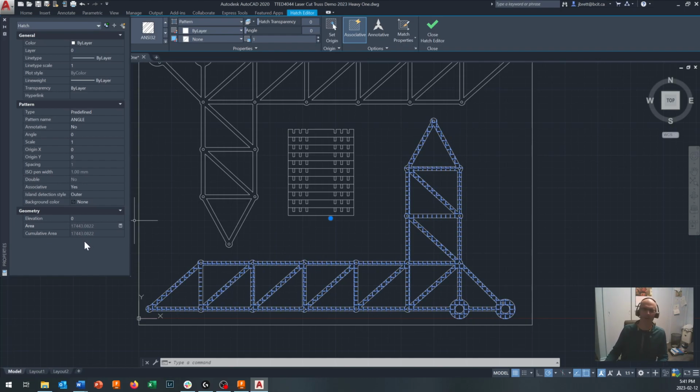You can actually determine that by taking a few very simple measurements in class. I'll leave that up to you to get a perfect value for the density so you can make a perfect mass estimation. But there you go. Just do a hatch and then the properties command, select the hatch. That gives you the cross-sectional area in square millimeters, multiplied by the thickness. Remember that you do have to convert from cubic millimeters into cubic centimeters, and that is not simply a matter of converting by a factor of 10. You have to think about what a square millimeter and what a square centimeter is.